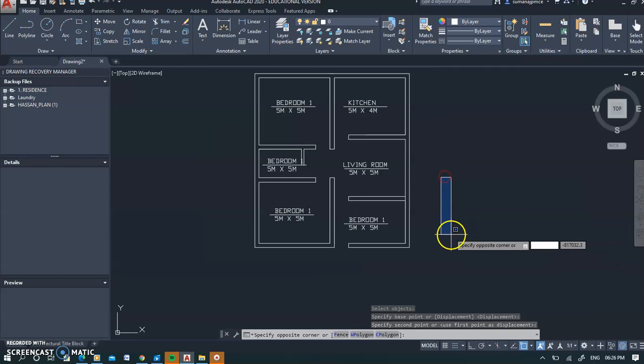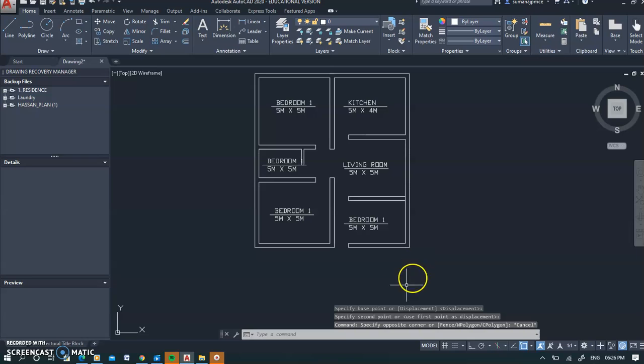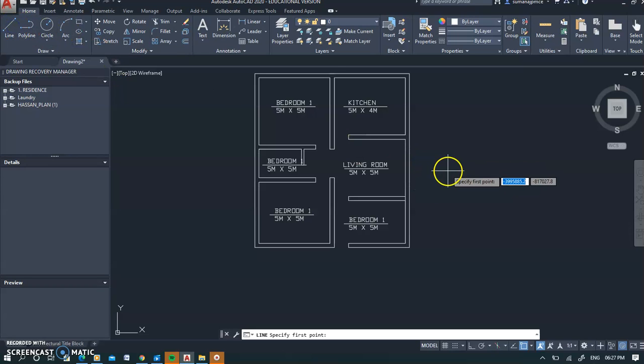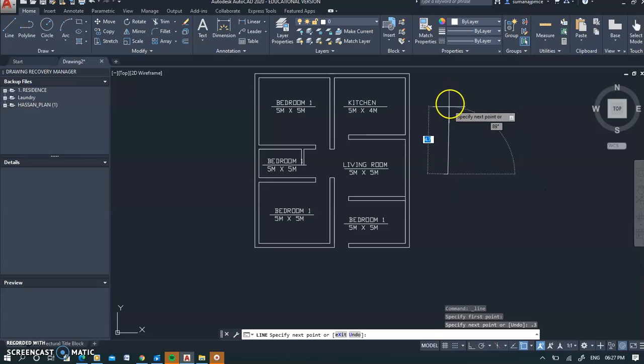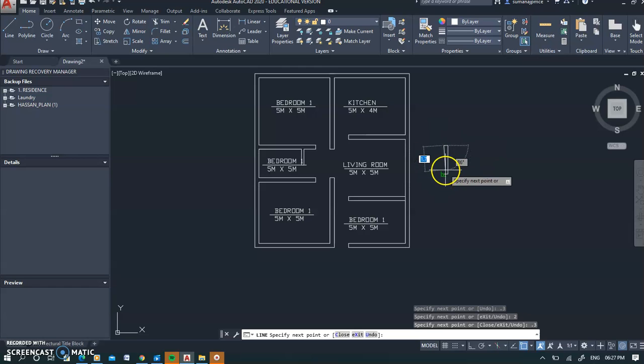like this and make it neat. So let's assume that you finished with all that, changing the letters. We will now draw the windows. So for the window, we need to draw the window size. First is the horizontal distance, which will be 0.3, as much as the wall. Then the length of the window, if you take the window to be, let's say, 2 meters, enter, and then come back here 0.3 and join here. Okay, that will be the window.